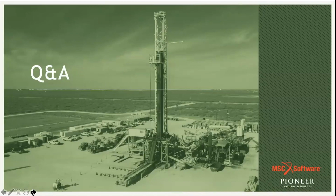I can add a little context to that. Part of the issue with running in real time and basically keeping up with the drill string is the amount of time it takes the solver to solve the equations of motion. And we're talking about thousands and thousands of equations at each time step. Obviously, if you have a shorter drill string, it's going to run faster. With shorter drill strings, depending on how you set up the model, you can run 10 minutes of simulation almost as fast as you can run 10 minutes of drilling. So it's pretty close for short drill strings.